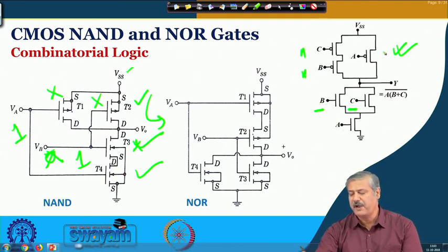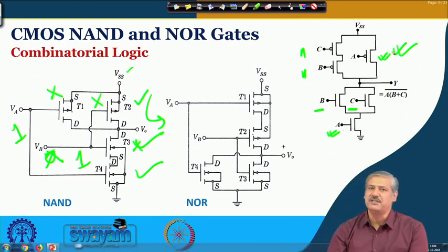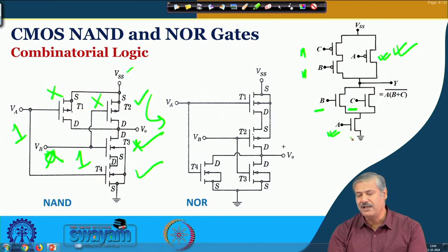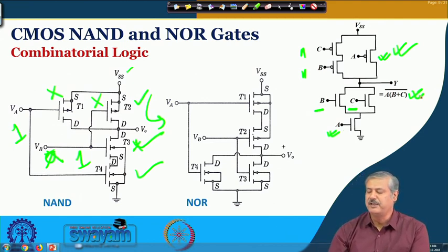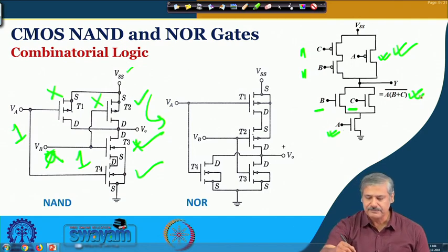So, that will be in parallel with what is there as A over here. So, that is how the combinations are formed, and this particular combination, right. So, this is B plus C ANDed with A, right, and there is that inverter. So, that is how you get the logic, and many such combinatorial logic can be developed by simple interconnection of this, which is much easier compared to what you had seen in case of other logic family that we had discussed.